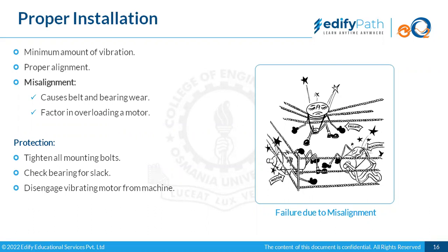So at every point of time when we are installing this, it should be ensured that we have installed it properly, so that there is no misalignment. Because with misalignment, the effect would be coming on the bearings, and if there is wear and tear of the bearings, then it would be affecting the rotor also in the long run.